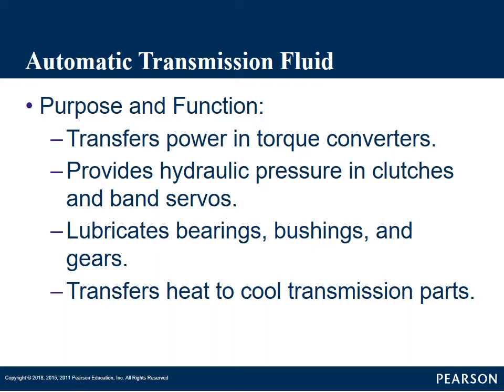It's a lubricant. All our bearings and bushings, gears, all that needs to be lubricated, and it's done through automatic transmission fluid. This automatic transmission fluid, when it absorbs the heat of the transmission, we run it through a cooler. That heat is then dissipated, returned back to the transmission, and then the process starts all over again.